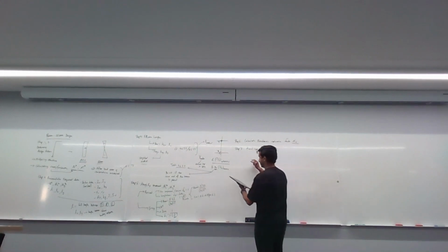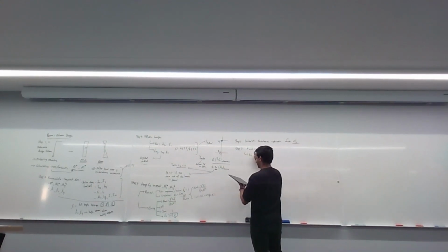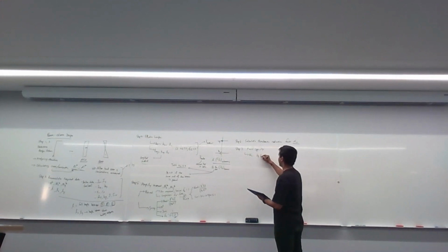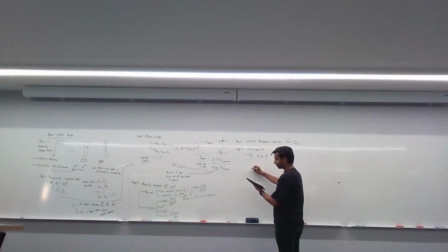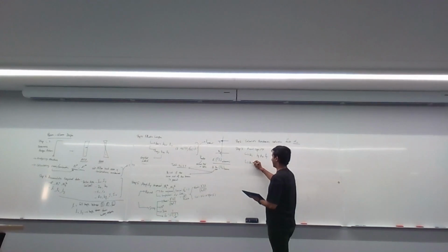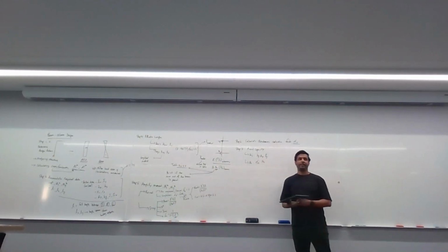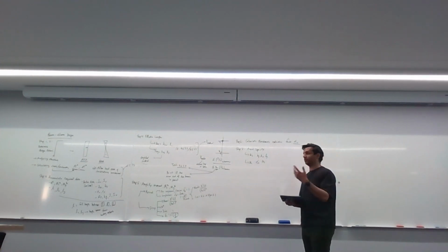I'm just going to give you the example here. Remember, the section capacity is determined as Kf, An, Fy, and then the member capacity Nc is determined by alpha C and Ns. Alpha C is your reduction factor to take into account the buckling.